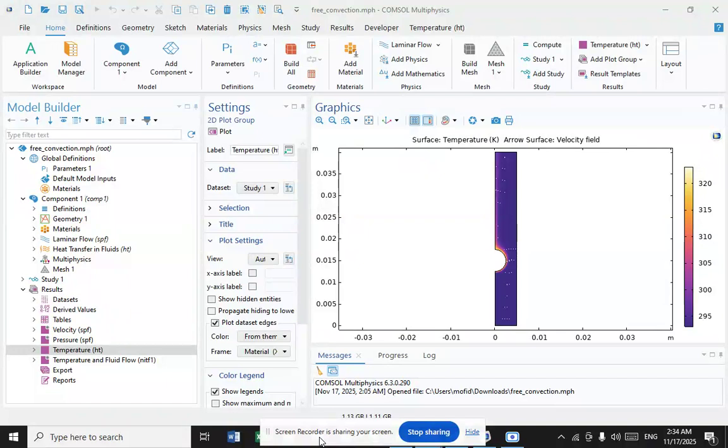It is intuitively apparent that flow and heat transfer will be strongly coupled in natural convection. Because there is bulk motion, natural convection heat transfer will be several times more than what one would obtain in molecular conduction. Even so, because no external agency such as a pump or blower is involved in natural convection, the velocities will be small, typically of the order of centimeters per second or tens of centimeters per second, as opposed to several meters per second, which is typically seen in forced convection.